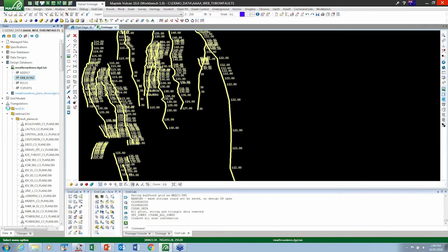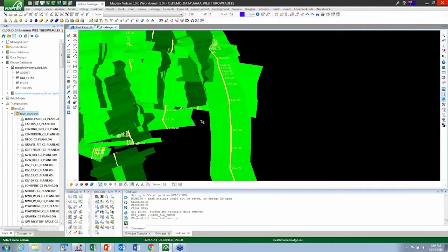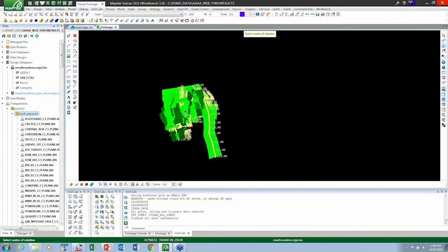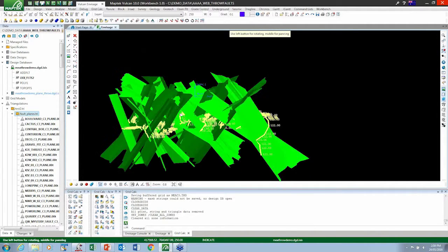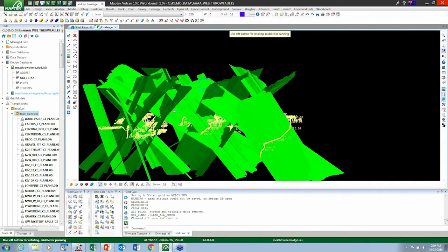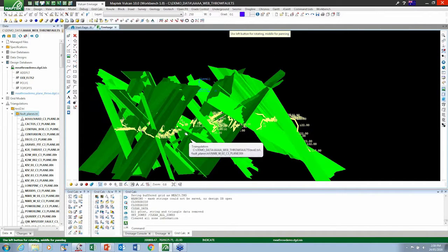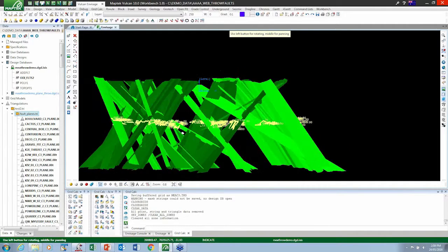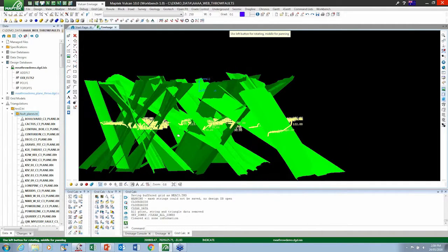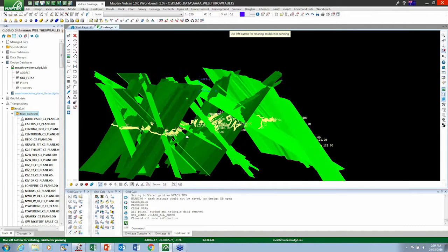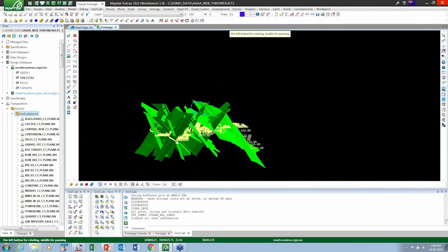So that's run, and I've run it over the entire area. So you see, for a start, it's thrown into this faultplanes.try directory the planes that it actually created for me. If I load those, you can see this porcupine effect here of all the planes it's used, in this case, on the C3 horizon. If you look inside there and think we're trying to make solid domains of that, that would be a fairly difficult job. So this gets around all that problem.